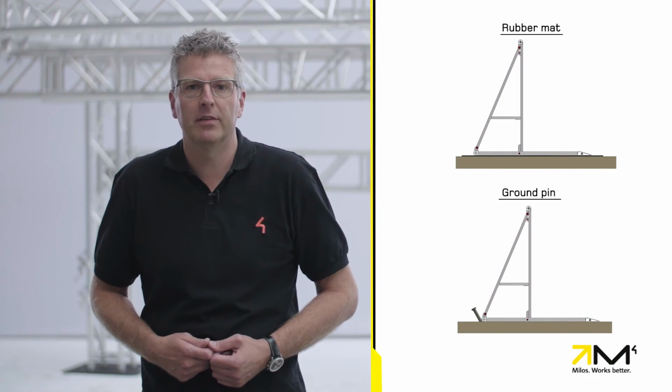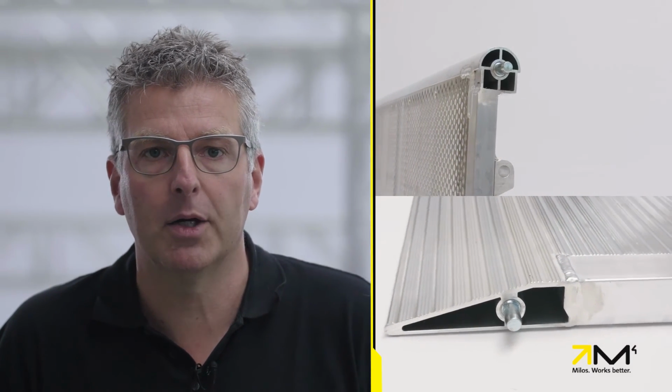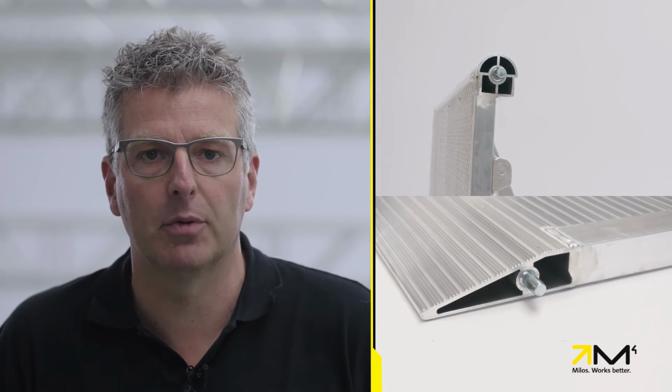Displacement can also be avoided by increasing friction between barriers and the floor they are standing on. This can be accomplished by placing rubber mats underneath or placing ground pins behind them. The horizontal top and bottom profile at the front or at the back are equipped with connection pins, which is essential to dissipate forces correctly. So always use a minimum of 2 connection points per barrier.